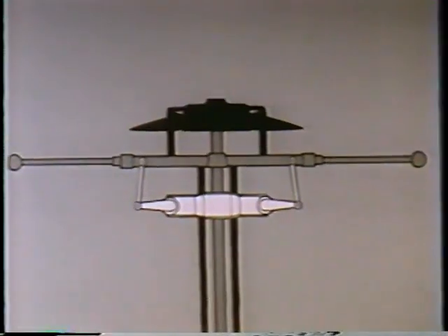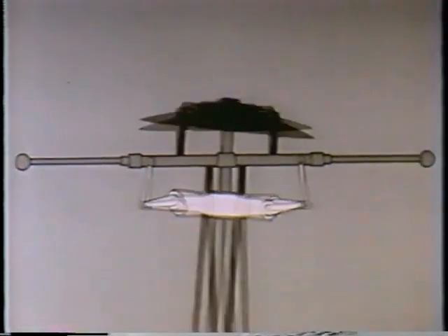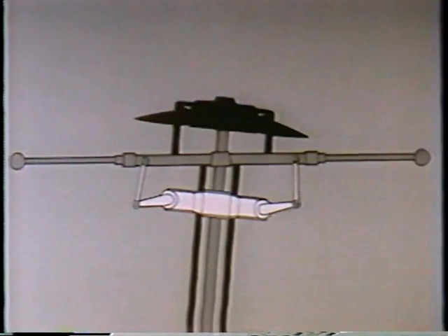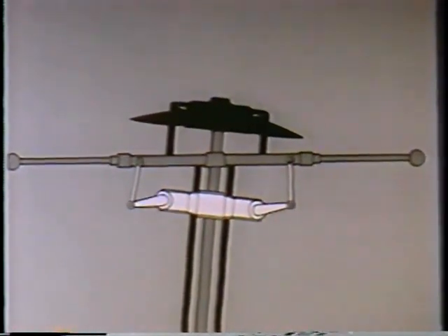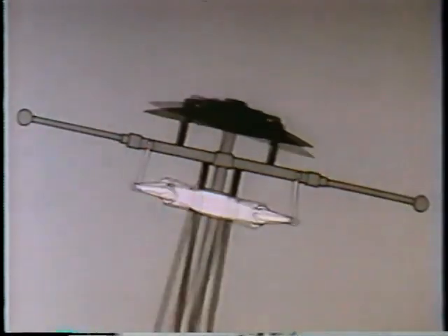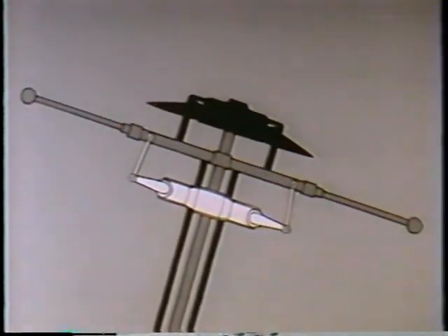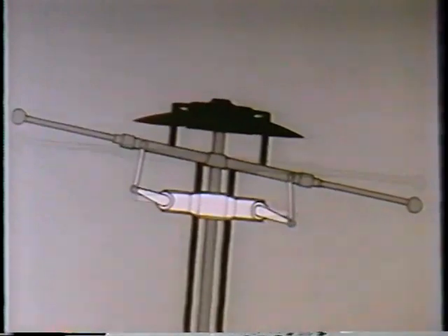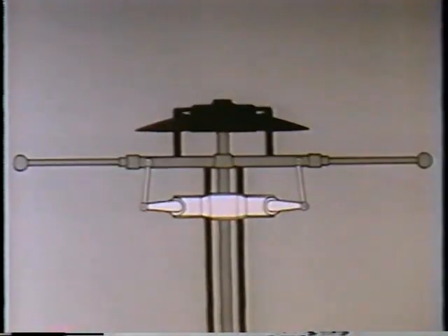When the mast is tilted in directional flight, the damper assembly is tilted with it. Since the stabilizer bar tends to remain in its same plane of rotation, the dampers immediately exert pressure on the bar, causing it to realign itself with the mast in 3 to 5 seconds.